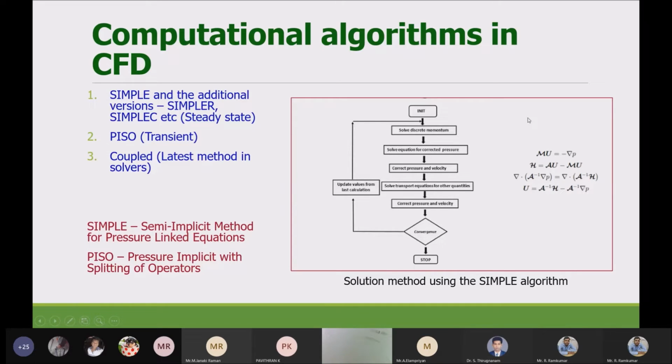So for flow, you have something called continuity, and then you have momentum. So what you will do is you will find something using continuity, put it into momentum. You will find one value. That value you will take and put it back into continuity. You will see whether both of these are equal. If no, then you will repeat.